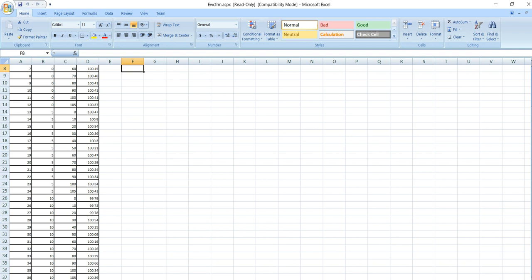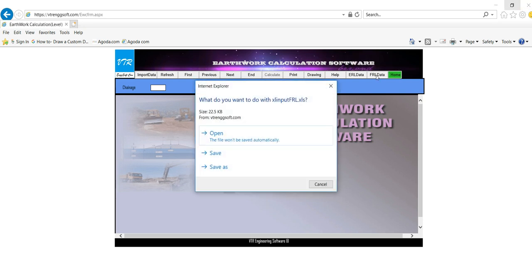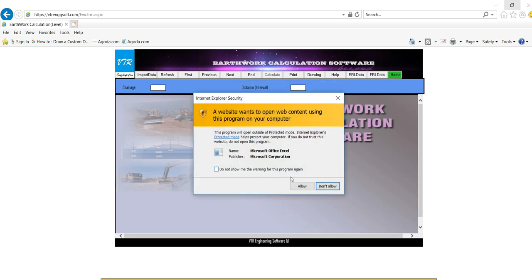That means the area where you want to fill up the earth, where you want to compute the earthwork quantity, we are dividing into so many sections. First section, that means the first chainage, we take the existing ORL, then the second chainage, and third, like that, going on. We are taking the levels and recording them, and it should be in this Excel format. Like that, we have to fix our finished reduced level. What should it be? The same way.